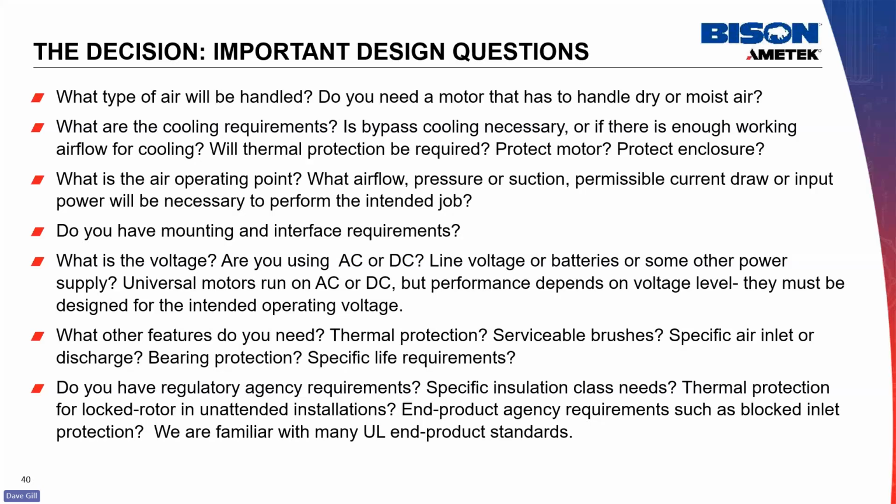What is your air operating point? What airflow pressure or suction is permissible? Or what is your permissible current draw at those values? Or what input power will be necessary to perform your intended job? Do you have mounting and interface requirements? What is the voltage? AC or DC? Line voltage or batteries or some other power supply?